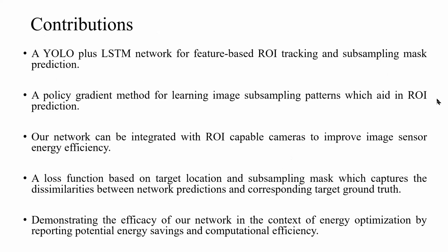These are the main contributions of my work. First of all, there's a YOLO plus LSTM network, which is being used for feature-based ROI tracking and spatial subsampling. And a policy gradient method is being implemented in order to train the LSTM network such that it is able to generate state control trajectories based on its learned parameters. Also, our network can be integrated with ROI capable cameras in order to improve the sensor energy efficiency.